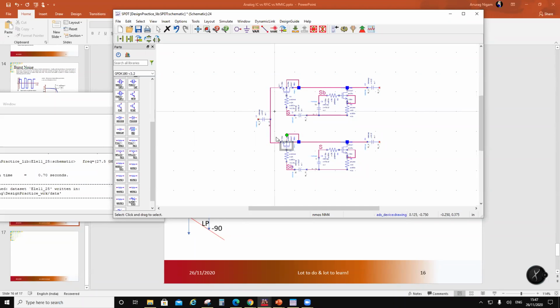So if this is through, and this one is a large transistor, there's a big capacitor here, and this one is on. So basically, your switch has two paths now. One is going between 1 and 2, which is what is desired. But what has happened is, as you start hitting it with power, more and more power is going to this shunt element to ground. And the only way to protect that was if this transistor was small. So for power capability, this transistor is supposed to be small, right? And you do not want to have a leakage path.